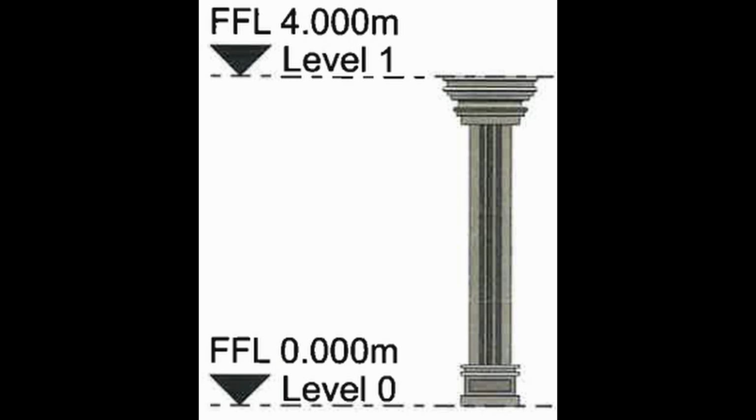When you swap one family for another, Revit aligns the new component to these reference planes. If a dimension references a standard reference plane, it will remain intact after swapping. If it references a custom reference plane, the dimension may be deleted.